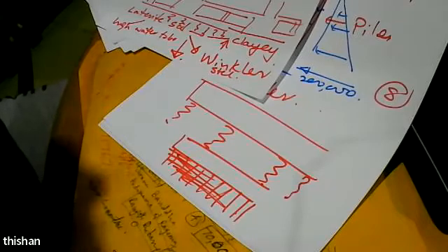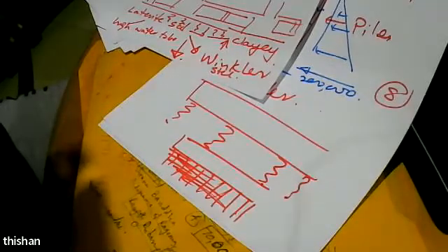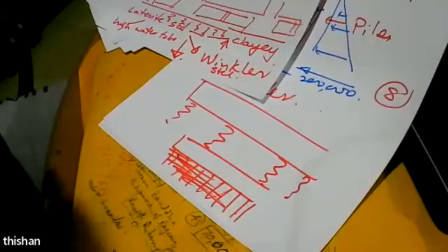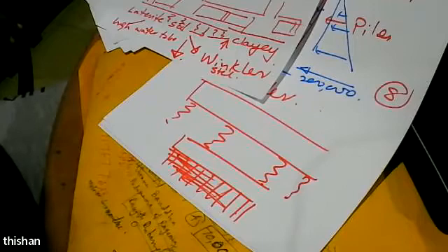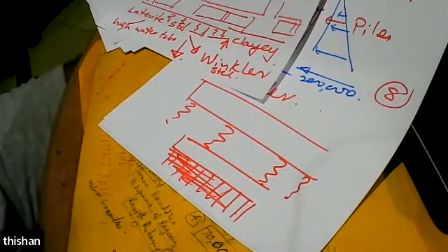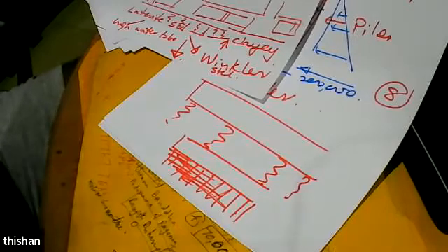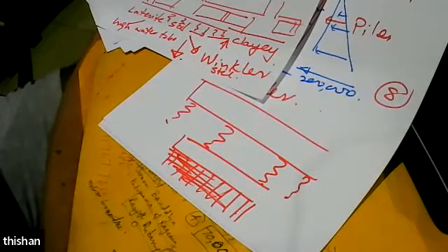It's a good material, but it's a little soft because it's a laterite soil subjected to high water table, because laterites contain a lot of clay, some 30 to 35% clay. This clay behavior can dominate the behavior of the soil. Whereas if you have a low water table, then the behavior of the sand will dominate, not the clay. And then we say you can analyze the raft foundation by using Winkler springs.